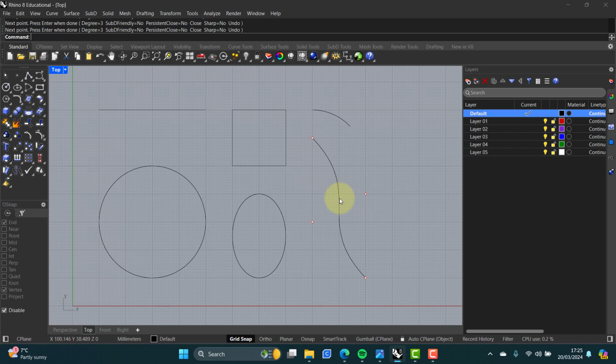Okay, if you click on the curve, you'll see how those control points behave. So this is basically the tangent. It sets up the tangent, but then when we choose the third point, it says, well, actually I need to now curve inwards to pick up the influence of this one. And then, okay, well, we're off back over to here to the end point, and so this is tangent as well. So it's usually the first portion and the last portion of a control point curve that are based on tangent. Everything in between is really dealing with curvature.